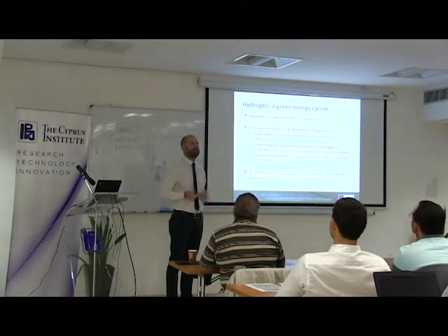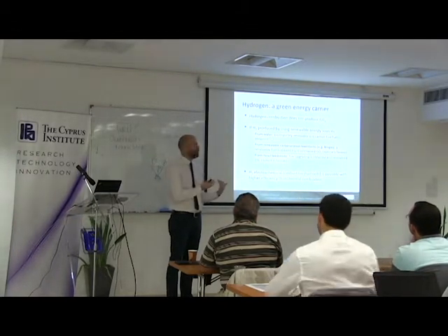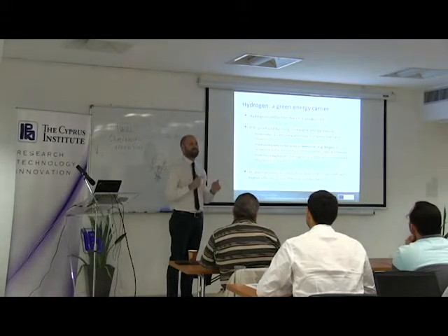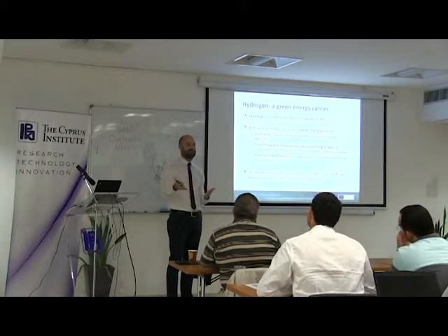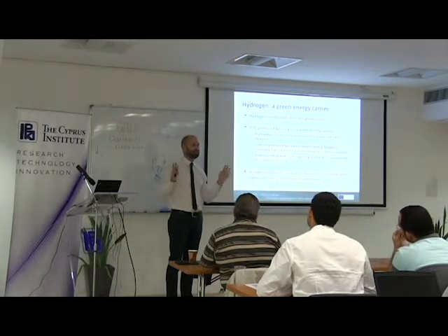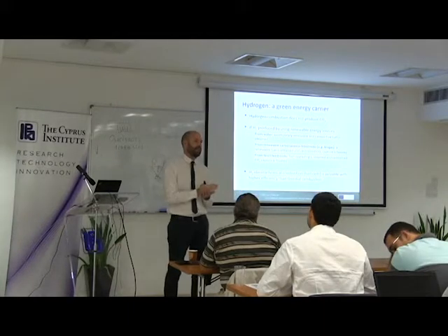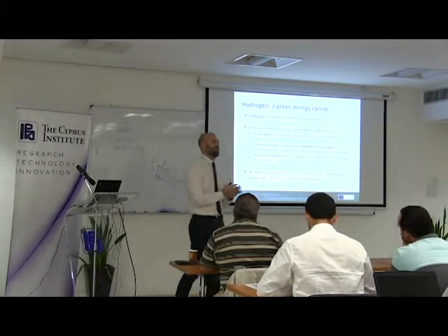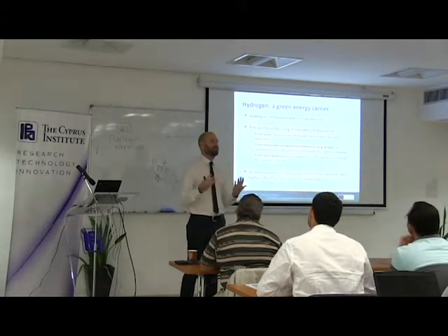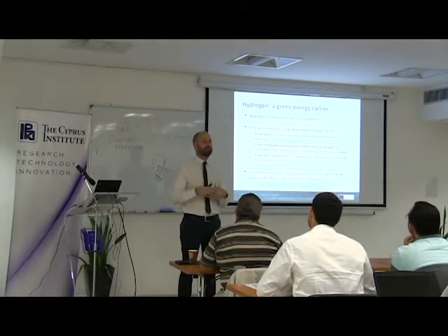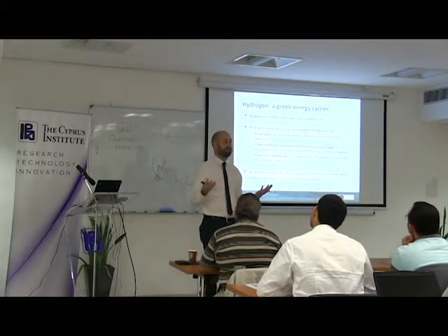What is the difference between burning hydrogen and then using this heat to produce electricity? If you burn hydrogen, you have heat, then you go through a thermal-electric conversion process like those we have seen this morning. And at that point, the second principle of thermodynamics will want its due. You have to pay to convert. You cannot convert 100% of heat into electricity, because the second principle of thermodynamics tells us that energy is conserved, but not all types of energy have the same value.